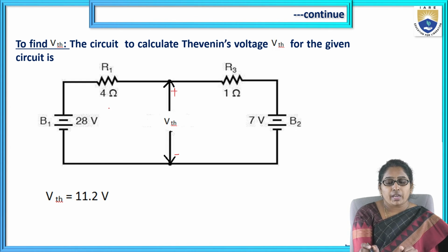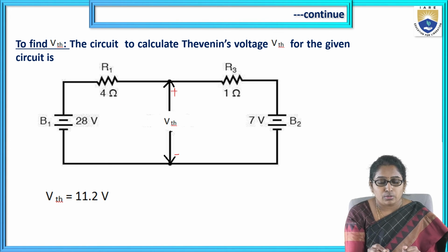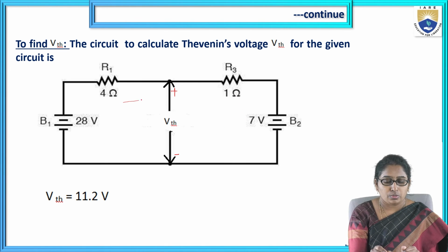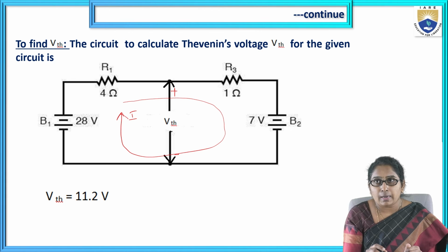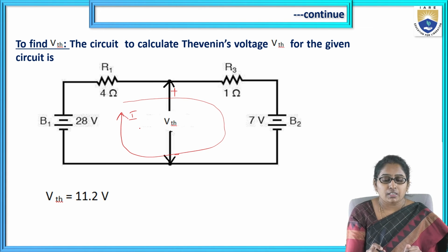Current-wise, the current flowing through each element is the same. There is only a single current path. So assume the current flowing in the loop is I, write down KVL and get the current in the loop.